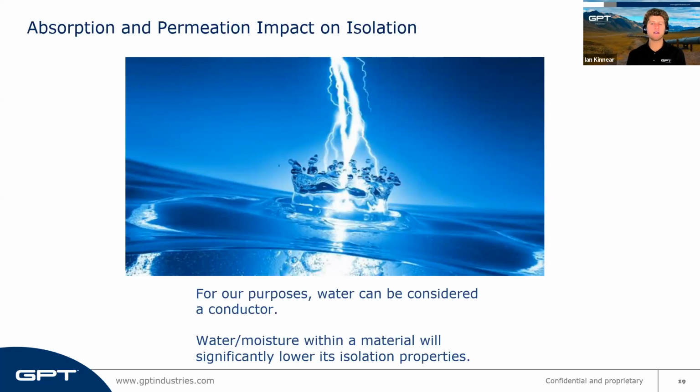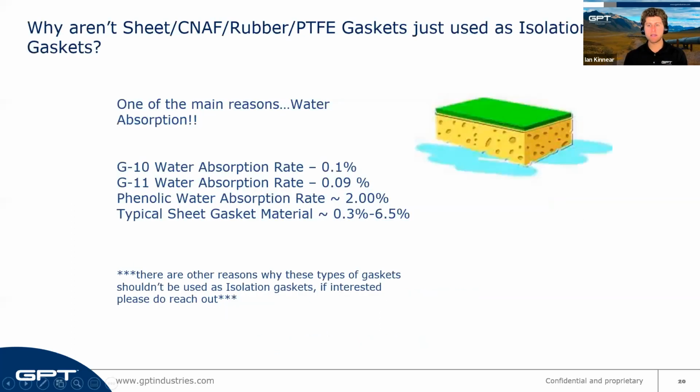And we also need to be aware of any type of media permeating into the gasket material, as this can have longer lasting effects in terms of chemical compatibility, material performance, and overall leak rates. The more we can avoid media permeating into and through the gasket, the more assured we can be that a proper seal is being made, and that the material would be able to perform through the life of a system.